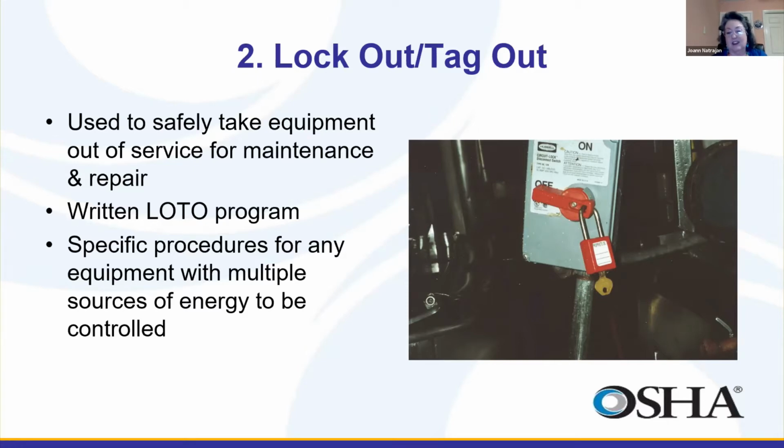Okay, in this case, one of the things you can see in the photo is the no-no: they left the key in the lock. That key goes in the pocket of the person that applied the lock. It's not to be left in the machine, because obviously anybody could come along, remove the lock, and just start the equipment. And that is not what you want to have happen while your guy is working on your equipment.